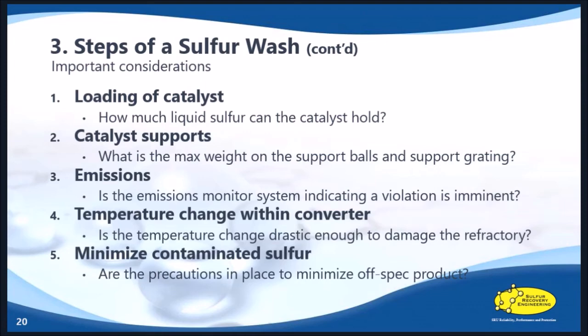Another thing to keep in mind, we're loading up a converter that wasn't designed initially to operate at sub-dew point level. We're not talking about a Sulfreen unit here, where the catalyst bed has been designed to hold liquid sulfur within it over the course of time. We're dealing with a converter that was designed to operate at a specific temperature. So you need to understand how good your catalyst support is, the supporting grating and the support balls, in order to understand, okay, am I going to do any damage while performing the sulfur wash?